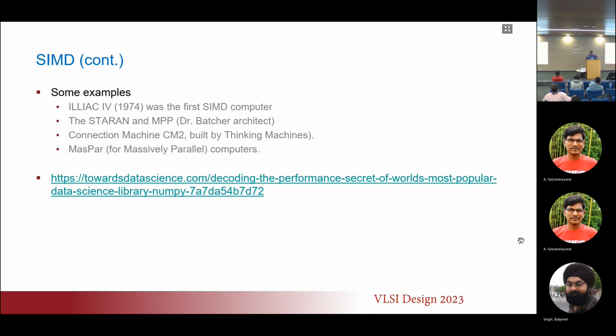And if I'm doing a dot product between two registers, it's one 8 by 8 tile with another 8 by 8 tile. And then I'm able to compute the dot product in one clock cycle and produce that output. Okay. So when I'm doing that, one of them is input, the other one is weight.